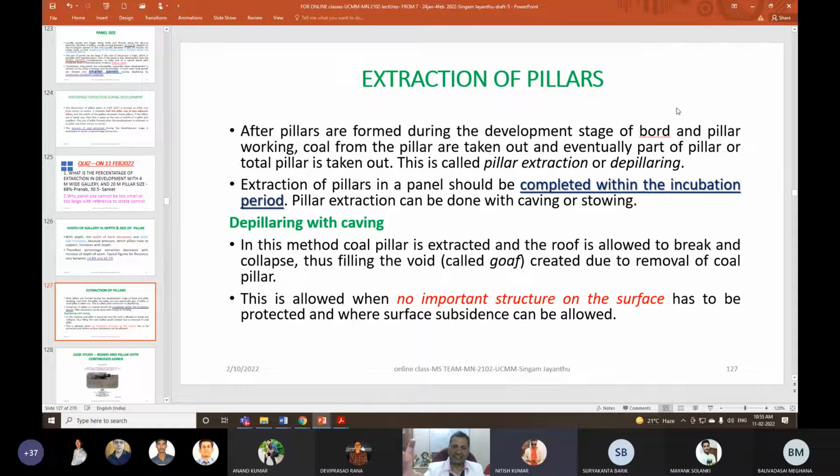I am taking out even a split, filling with a backfilling material which is as strong as that coal, with some cement, with something else, whatever it is. Then splitting it and filling it with that, and the adjacent material of coal I can remove. In that way I can remove everything. But you can imagine how costly it is. That is the reason why even stowing also is not very much practicable in many situations.